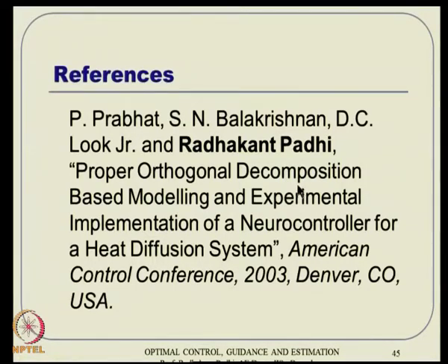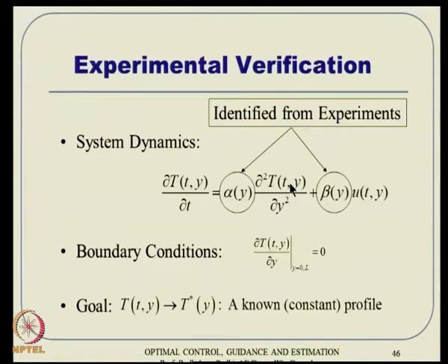But ultimately, the first problem in any experimental validation turns out to be the modeling accuracy. What we conveniently assumed as alpha equal to 1, beta equal to 1 in all our math analysis is not true. And in general alpha and beta are not even constant, they are actually functions of y. So, this system identification is the first thing to do, and that itself was a procedure actually.